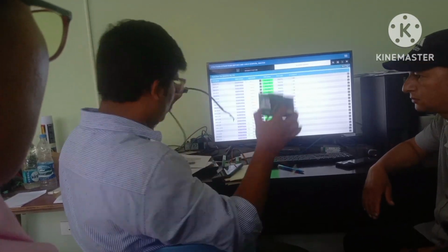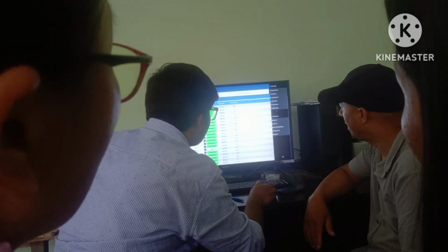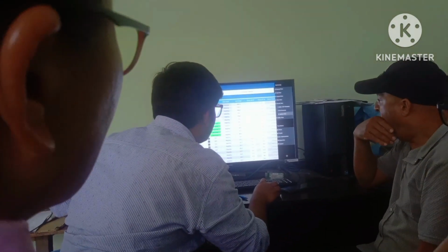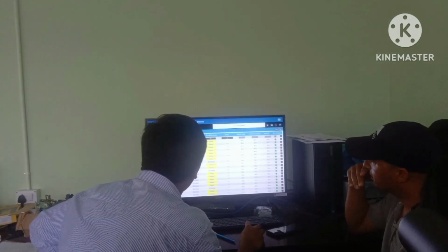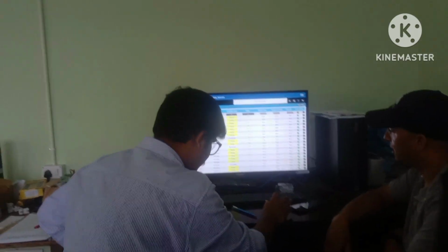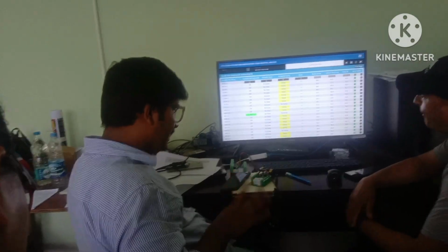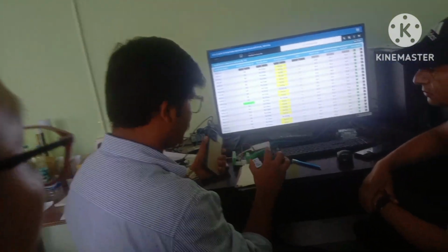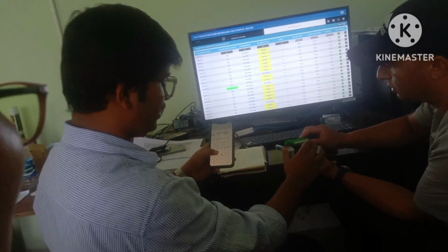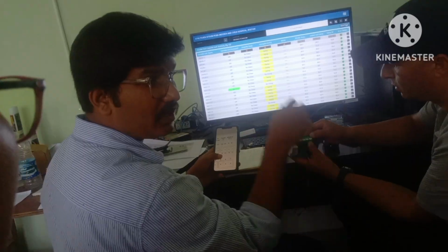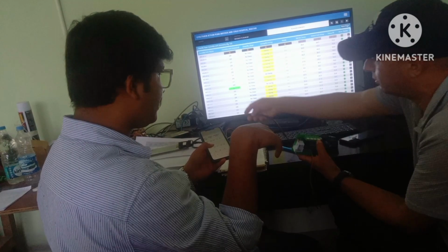If you see, I think yesterday there was one device, the cassette. Are you able to see all the hazard warnings? That means that specific cassette is not communicating. That means either the Modbus port, see this Modbus port, A and B, 14 and 15, has a loose connection, or is not connected, or there must be a fault in that device.